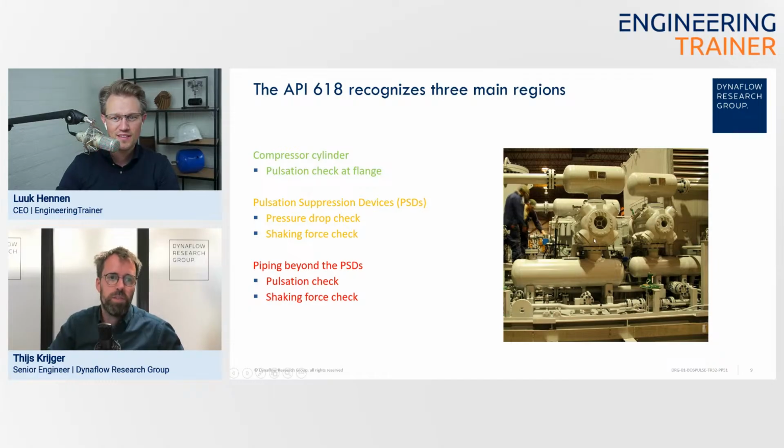Especially if you have a compressor system that has to operate not just for one type of gas, but for multiple gases, or other differences in operating conditions, it might be impractical to design a system that has that pressure drop met for all different operating cases. In those cases, probably aim for having it be as efficient as possible for the case that's the most likely, or the system will operate at the largest part of the time.